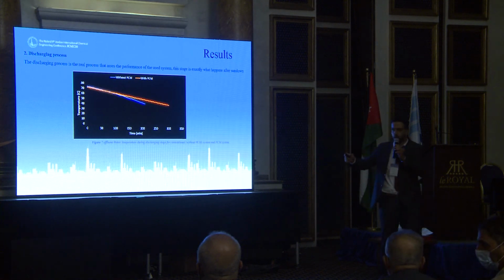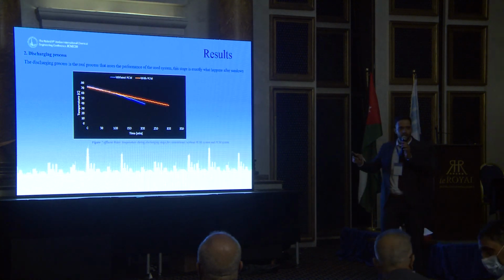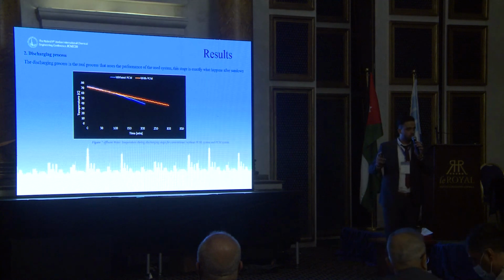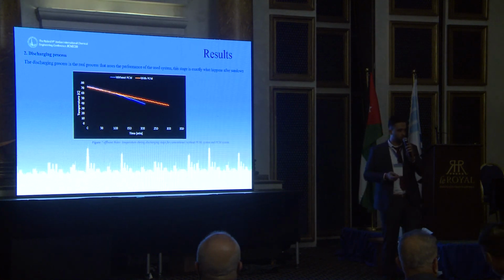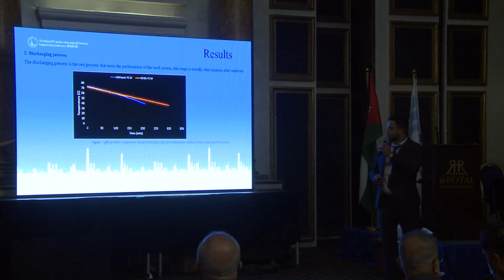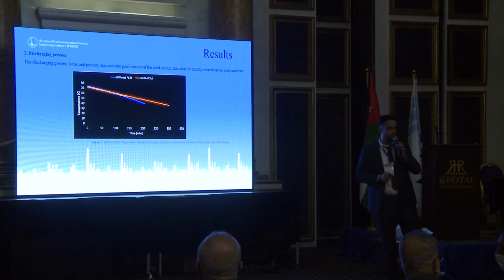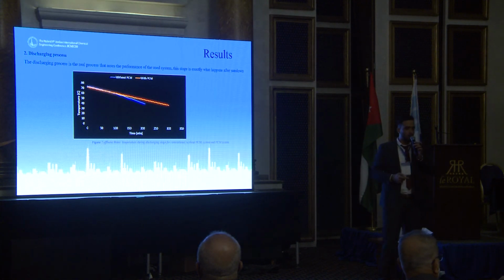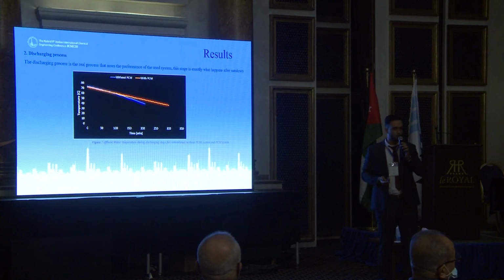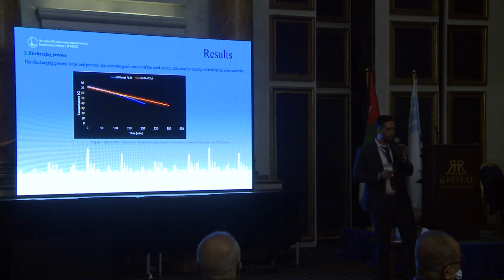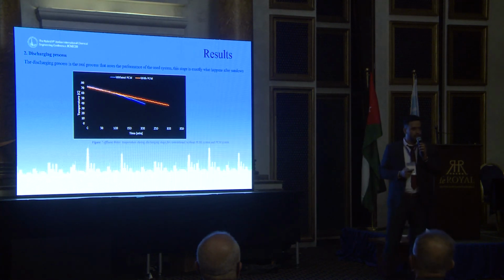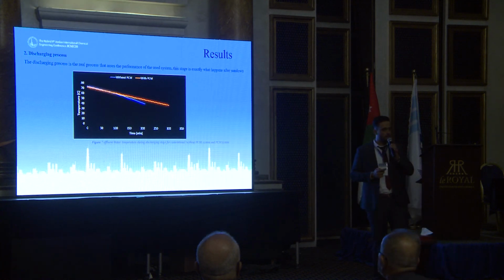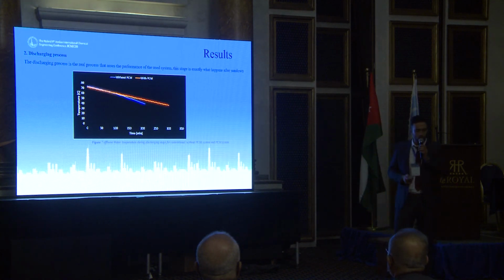for the consumer. With phase change material, it took more than 300 minutes of hot water supply to the consumer. The conventional system took around 200 minutes. So we have 1.5 hours more of delivering hot water to the consumer, and this is the advantage of phase change material: store the energy at peak time and reuse it when there is no sun.